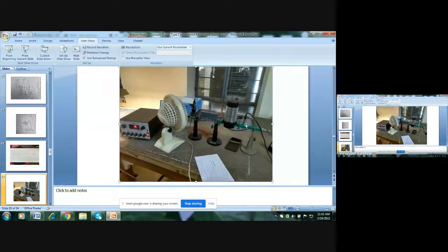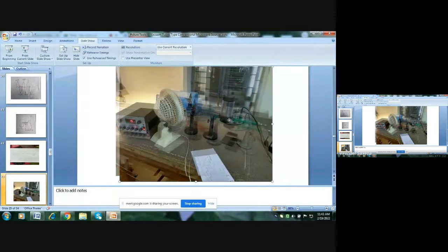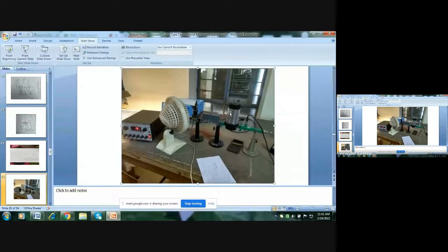And this is the frequency meter, direct reading frequency meter. The working of this frequency meter is that we have placed this frequency meter in the path of RF field. Means microwave power is traveling from Klystron to the detector, and there is a waveguide and a tuner. Means a cavity is fixed in this frequency meter, and this coupling is through a hole. There is a hole in the bottom of this cavity, and this hole is connected to the waveguide.